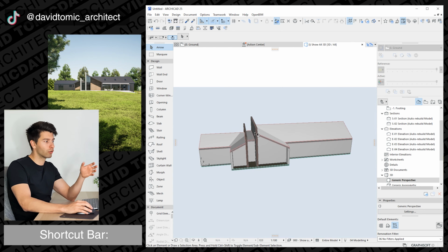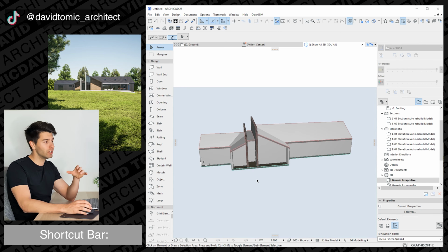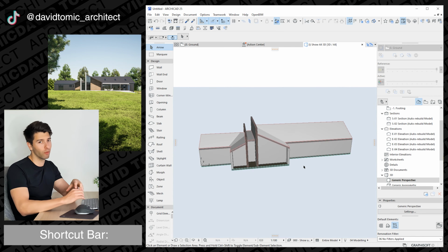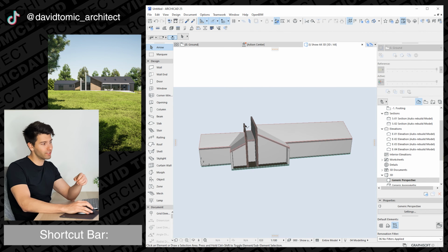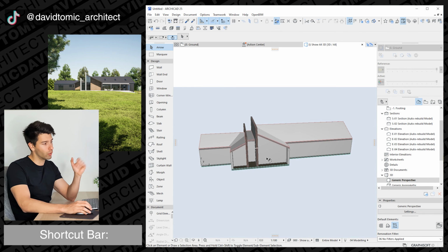So the two concrete mass thermal walls are basically going to radiate heat into these two spaces, especially this larger public open space that is one grand void with raking ceilings, while still allowing northern light through the extended concrete blade on the right hand side.